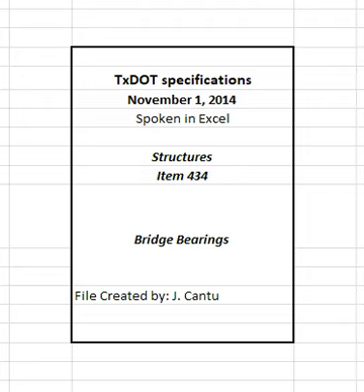3.1.3 Documentation. Furnish certified laboratory test results on the elastomer properties of each batch or lot of compound for both plain and laminated bearings. Provide copies of certified mill test reports for laminated bearing steel top plates and any required steel special components. 3.1.4 Storage. Protect plain and laminated bearings from sunlight until placement in the structure.